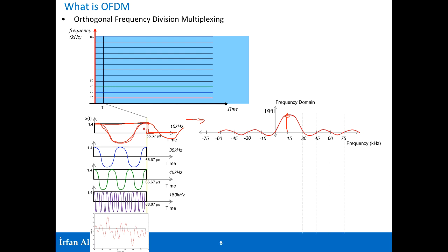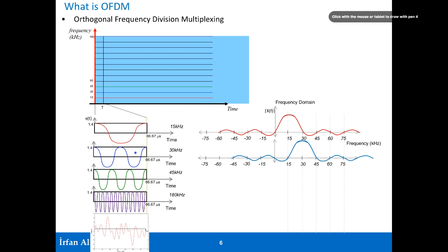And essentially, if you take the Fourier transform of your 30 kilohertz, you'll get the same thing, but centered now at 30 kilohertz, a sinc function that goes on in the frequency domain to infinity, but centered at 30, and so on. And then for the 645 kilohertz, you get something like this.